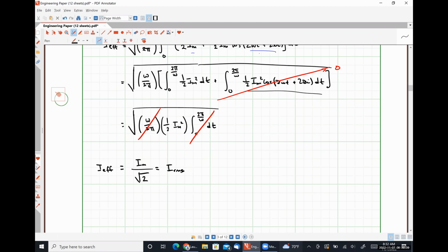because it doesn't matter if you're here in the United States, where we deal with linear frequencies of 60 hertz in our transmission and distribution systems, or if we're in Europe, where they deal with 50 hertz in their transmission and distribution systems, or in Japan, where they use both, depending on what side of a river they're on. Totally true. The effective value of a sinusoid is always just the magnitude of the sinusoid divided by the square root of 2.